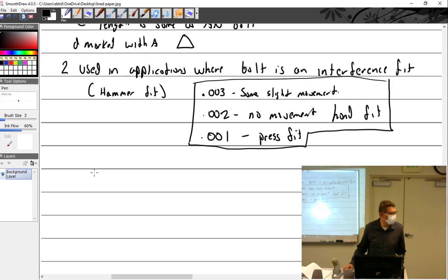What would be the point of the interference? You don't want it to move. Okay, well, like in engines. You haven't had engines yet, right? No. Okay, we have the connecting rod. So the big end goes on the crankshaft, and the small end is where the piston pin goes in. There's a bushing that goes in there. There's a lot of parts where a bushing goes in. The bushing is actually bigger than the part it's going into. So when you push it in there, you use a press to get it in there, so it can't come back out. So bushings are all press fit.